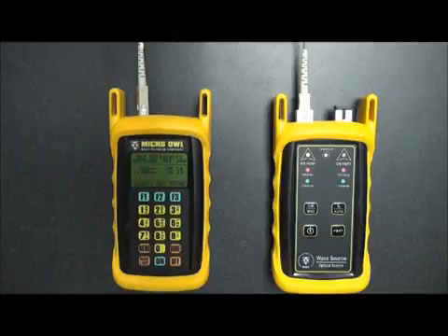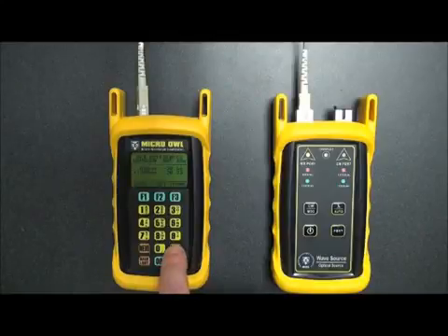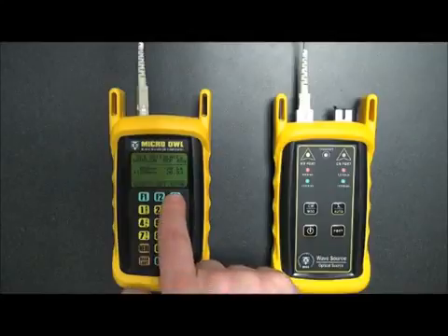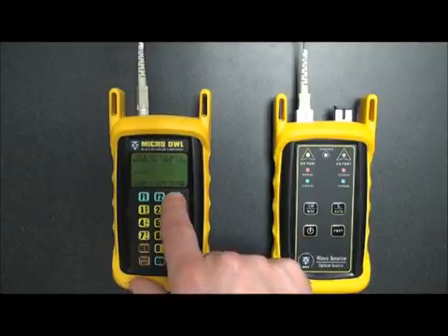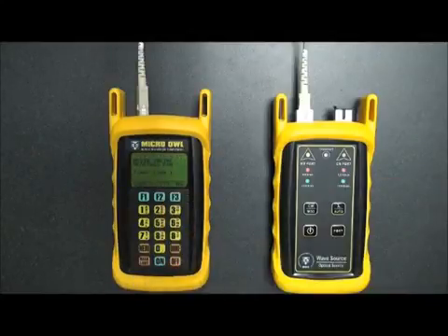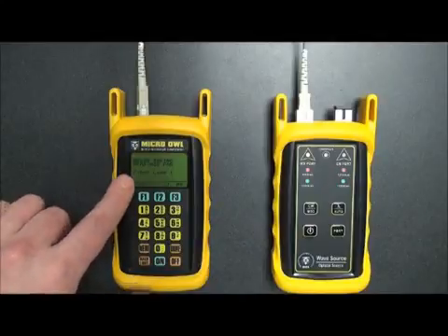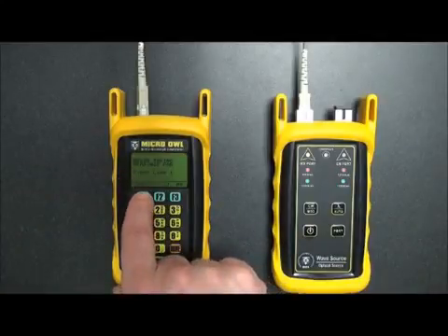One helpful tip is to check your patch cable before you begin to make sure that you actually have zeroed and nothing else is going on. So in order to exit the set references screen, simply press the done key, or you can press F3 for done here. And it'll say begin taking readings for our fiber link number. So you press yes to confirm that.